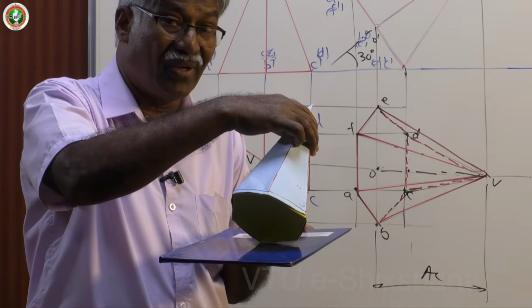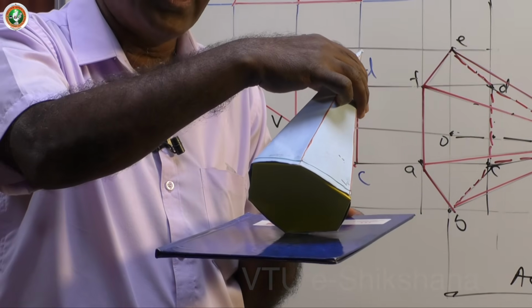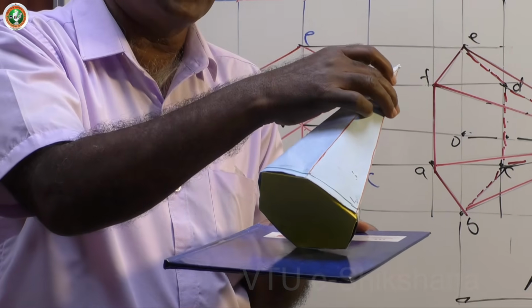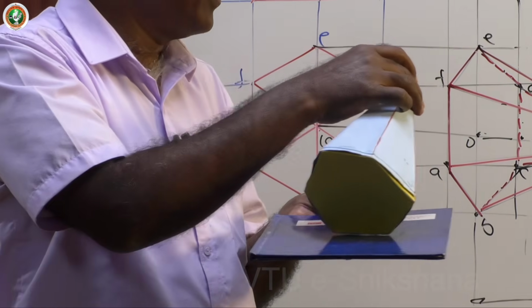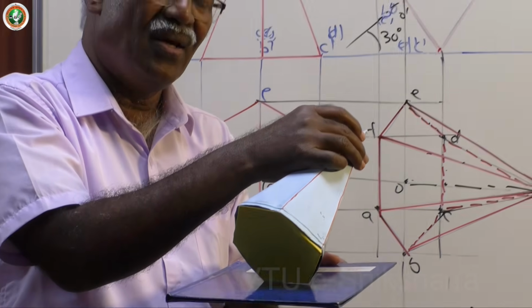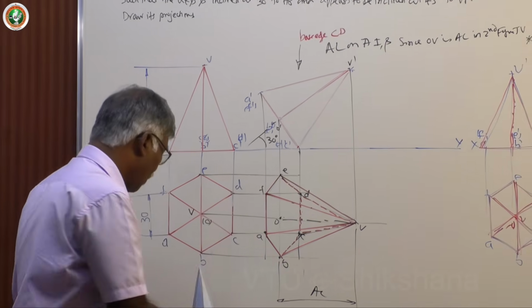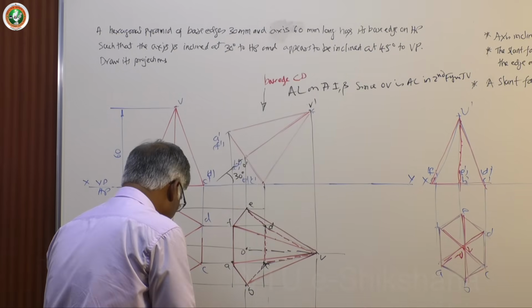So the base is completely visible. That is, the nearest surface is the base, the key surface is the base. Then the farthest item from the observer is the apex. Then there will be confusion in keeping. Now in that case, for finalizing the final front view, you can use the key surface method. So now I can start working for the final front view and top view.